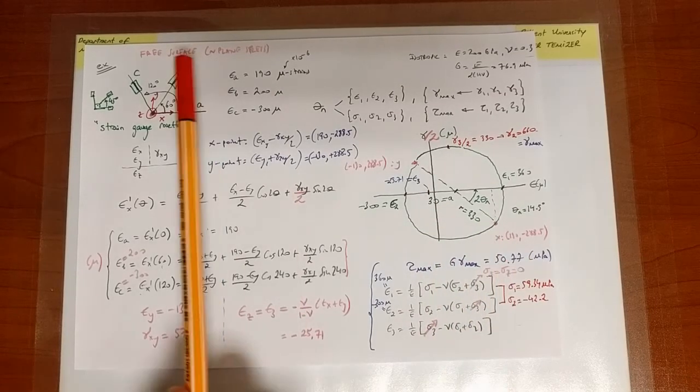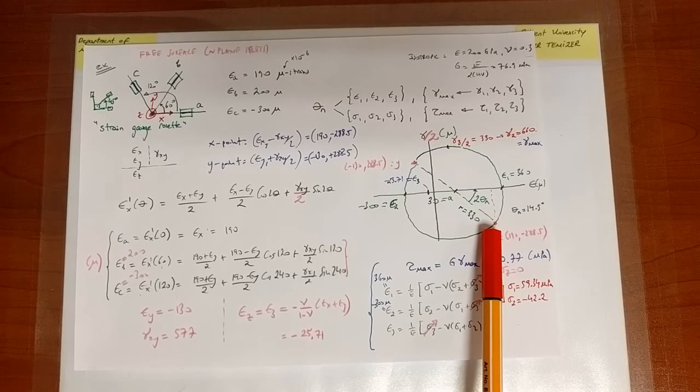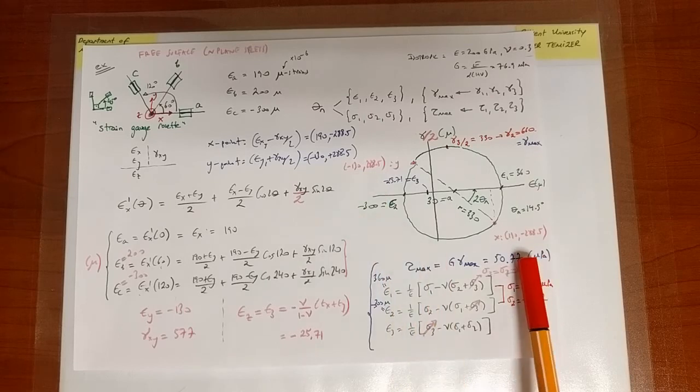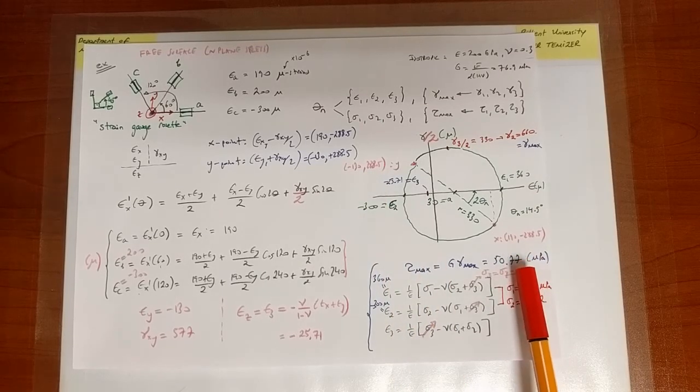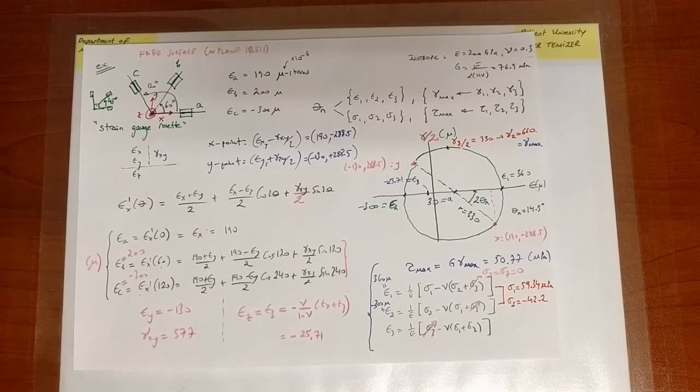Well, to do that, I do a strain measurement, and you see, based on the equations that I have access to, I can calculate the state of stress with respect to the XYZ axes. I can convert that picture to the principal picture and go for, say, the maximum shear strain, and thereby extract the information that I need. The information that I needed might have been the maximum normal stress and not the shear stress. In that case, I can extract that information as well and use that towards material failure, which we're ultimately going to do in the next topic. So that's why this is a nice example that takes us all the way through what we've done so far in the course and connects many concepts together.